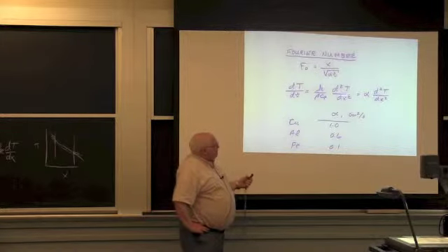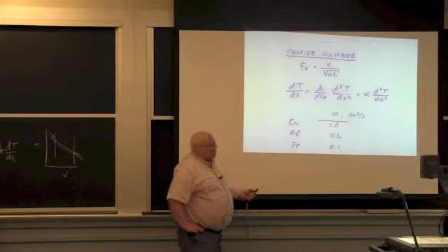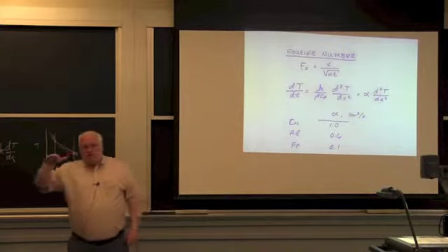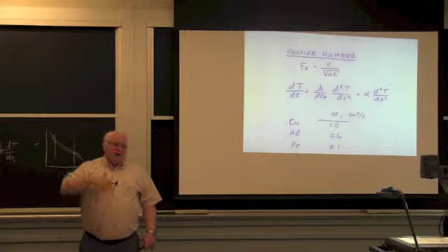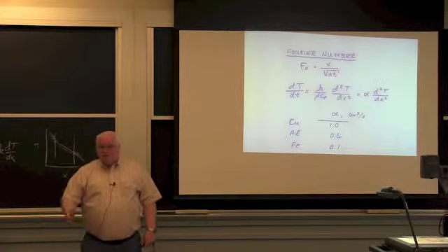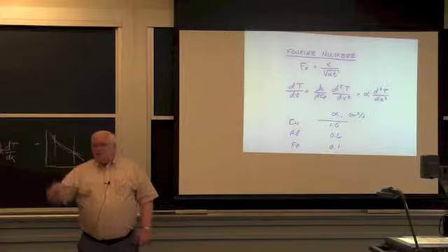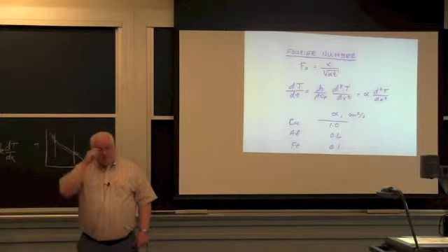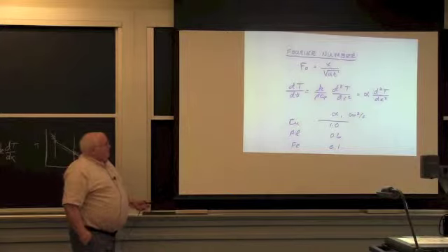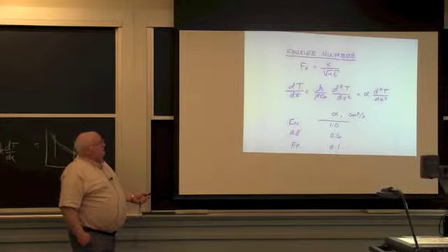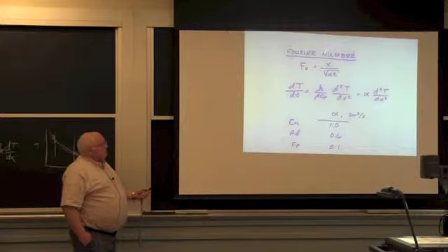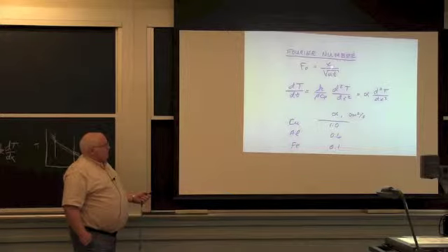You can show mathematically, and they taught me over in the math department, that you can do a dimensional analysis on this, and you can show that whatever solution you have, whether it's an error function solution, an exponential, a Bessel function in cylindrical coordinates, a Bessel function in spherical coordinates, all these fancy things that go into these big textbooks on how to solve this in different geometries and different coordinate systems, they always will have an argument of the exponent or the Bessel function or whatever in terms of a dimensionless number, in this case called the Fourier number if we're talking about heat transfer.